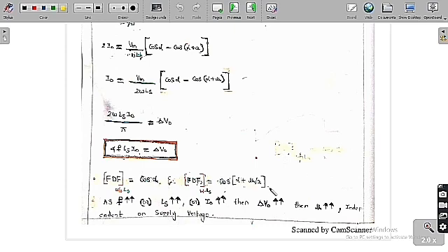Then what is going to happen? As the frequency increases, or the source inductance increases, or the load current increases, if any one parameter increases, then definitely delta V0 increases. As delta V0 increases, mu is increasing, which means the overlap is increasing.